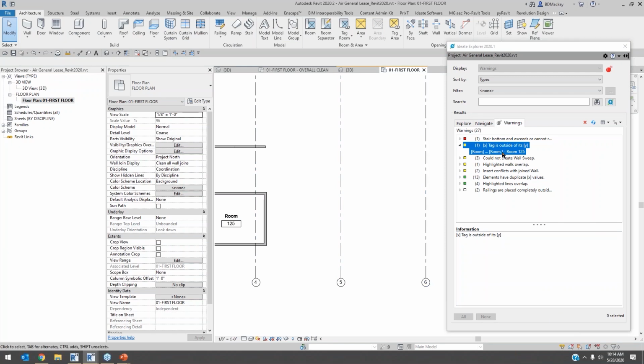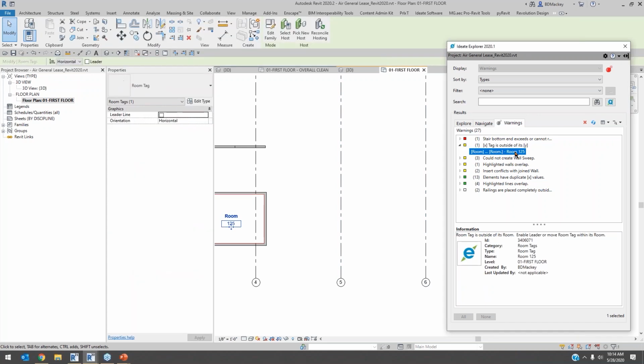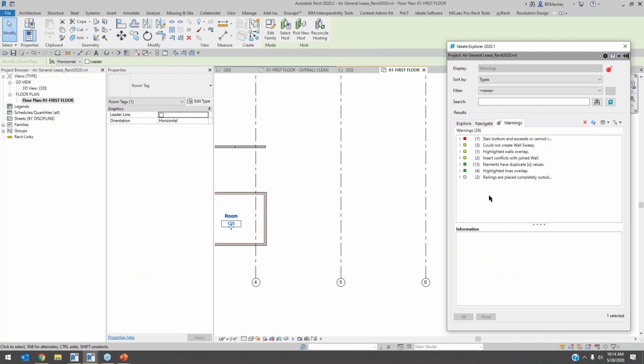So some of these things like that, you can say move to and fix really quickly by using the Revit tools. Now you also notice that I had to hit refresh a second ago. Some of these things you fix, and you're like, wow, it's still showing that. Didn't I fix that warning? What's going on? You can see that now if I select that, I don't get to show related warnings. So you do have this refresh button up here.